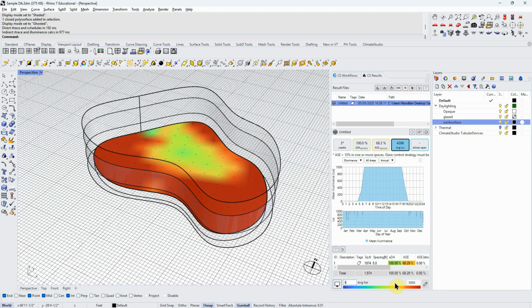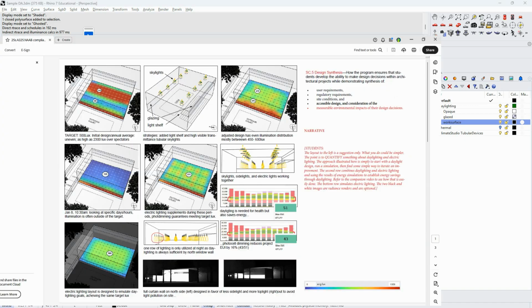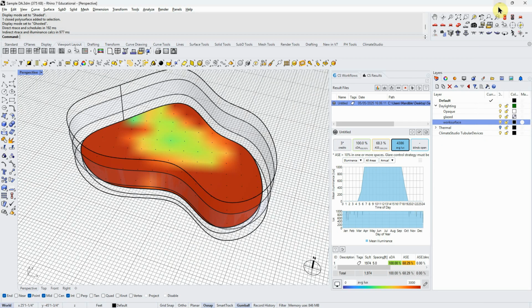You can change this as much as you want before you're actually comparing things, but once you're comparing, you want it to be the same range. And you need to always show that range. So for example, I just put mine down here. Maybe that's not the best place, but we're measuring, we're quantifying. We need to understand what these colors mean. They can't just be colors, so they need to be associated with numbers. Okay, so I ran that simulation. We've got actually a huge amount of light, 10,000.